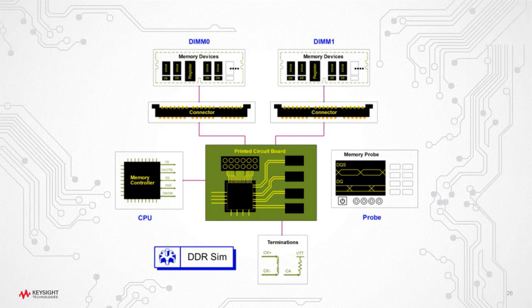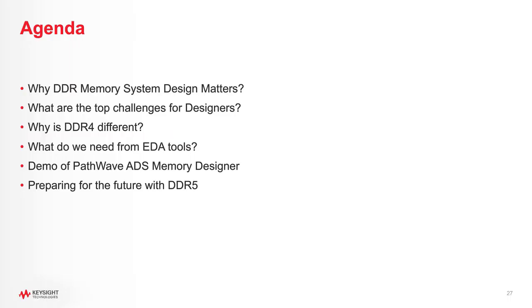The memory controller, you assign your IBIS models directly as groups. We use information from the layout to automatically connect pins from the PCB to the memory controller. And we've got a brand new memory probe that gives you access to each and every signal inside each of the DDR components without needing to wire anything up. So let's take a look now at a pre-recorded video demo of Memory Designer in action.